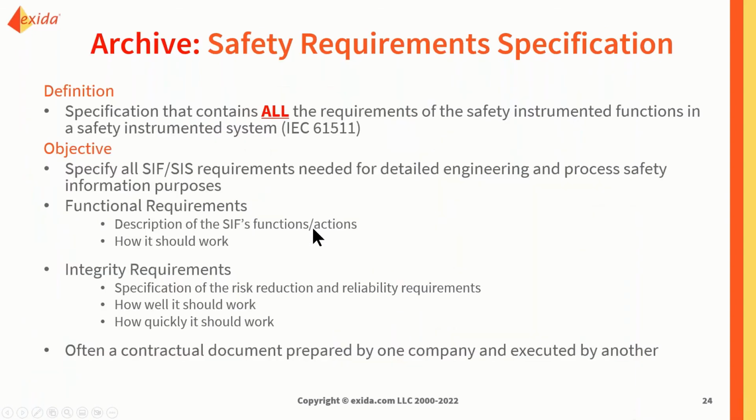So as you can see, the main focus of that particular lifecycle in IEC 61511, everything actually goes back to the safety requirement specifications. In fact, it is something that is actually required and also very, very important in IEC 61511. It should contain all the requirements for the safety instrumentation, safety instrumented systems, and safety instrumented functions as well.